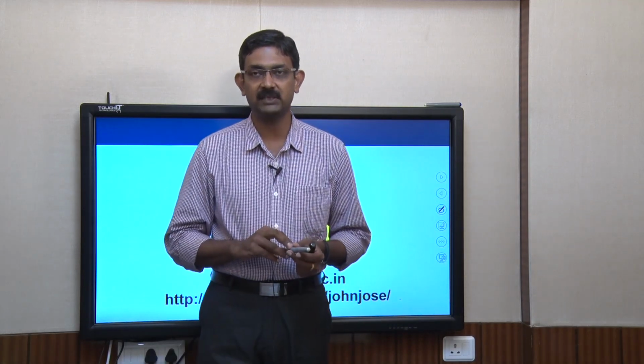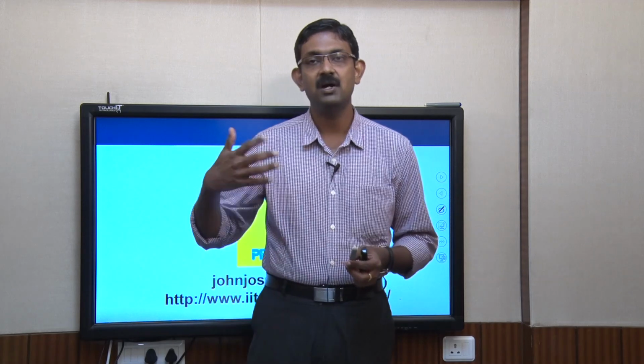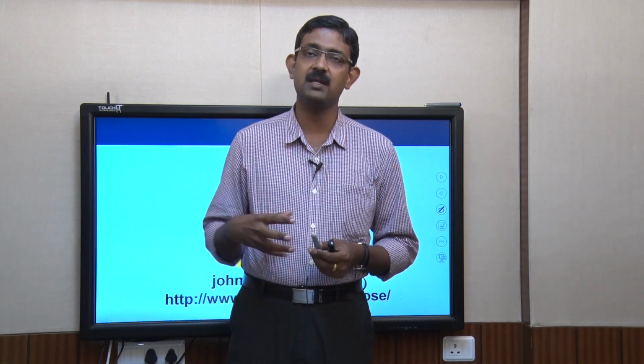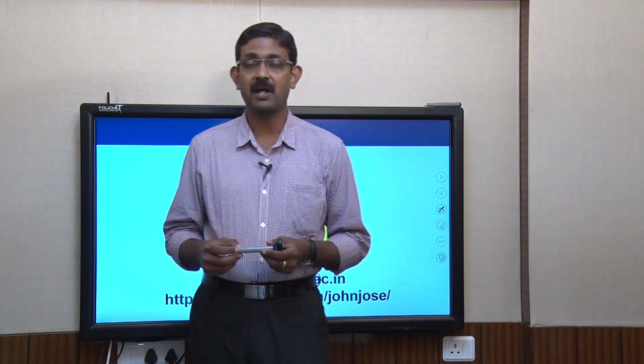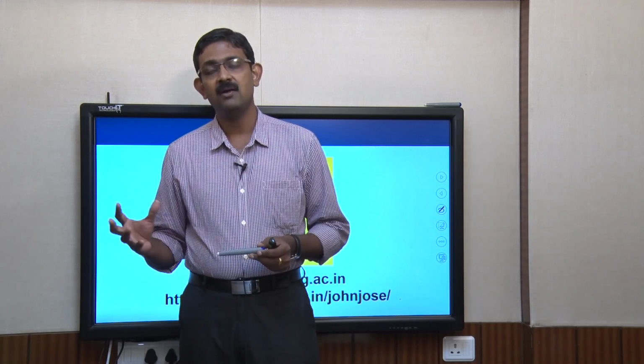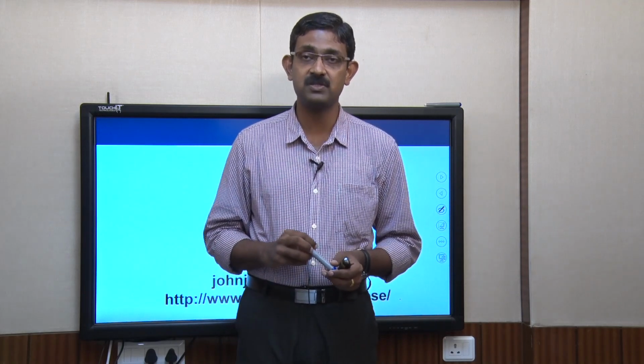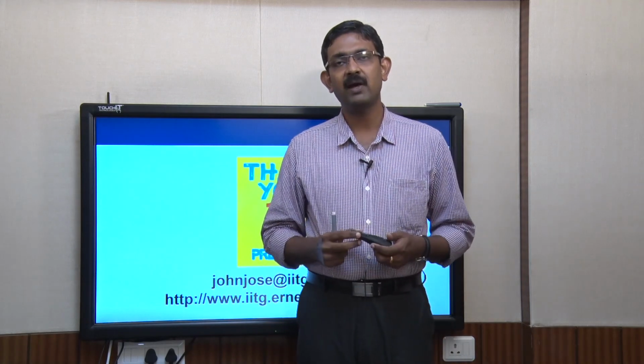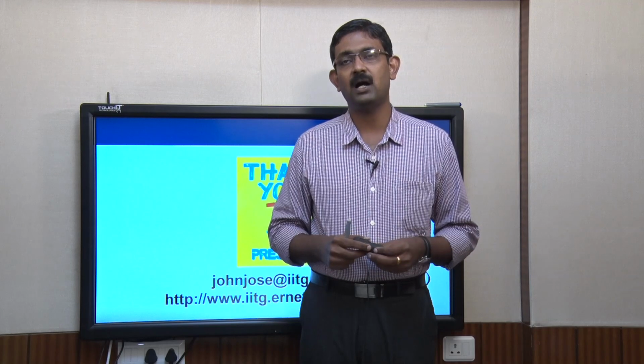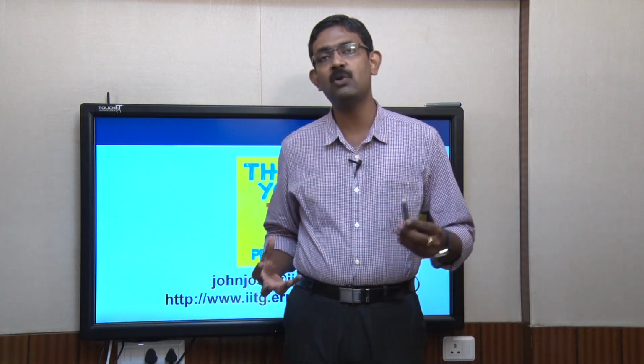So, today we had a discussion on minimally buffered deflection routers. Basically, they are side buffer deflection routers. We saw what the limitations of Chipper are and came up with the MinBD router. The MinBD router was basically focusing on introducing one more level of priority called the silver flit mechanism, and then we have a buffer eject unit which will accommodate flits in the side buffer. So, the concept of side buffer was first introduced by the MinBD router design, and then you have the dual ejection bandwidth. Now, finding out some of the limitations of the MinBD router, the D-bar router was proposed, which has a hybrid ejection unit and a dual injection unit which will give equal preference to injections from the side buffer as well as the core buffer.